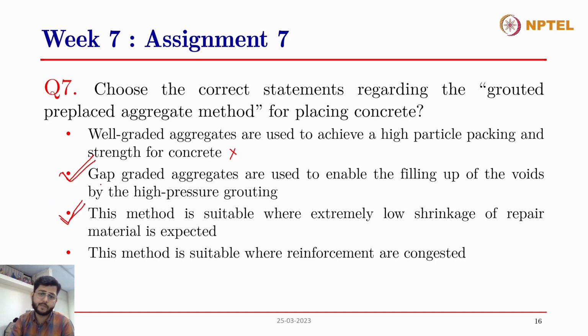The last option is this method is suitable where reinforcement is congested. No, because we have to place the gap graded aggregates. The gap graded aggregates should, of course, be less than the size of the gaps between the reinforcement. But since we are placing them initially, a high amount of congestion of the reinforcement will hinder the placement of these gap graded aggregates, and therefore this method will not be suitable for a location where there is a congestion of